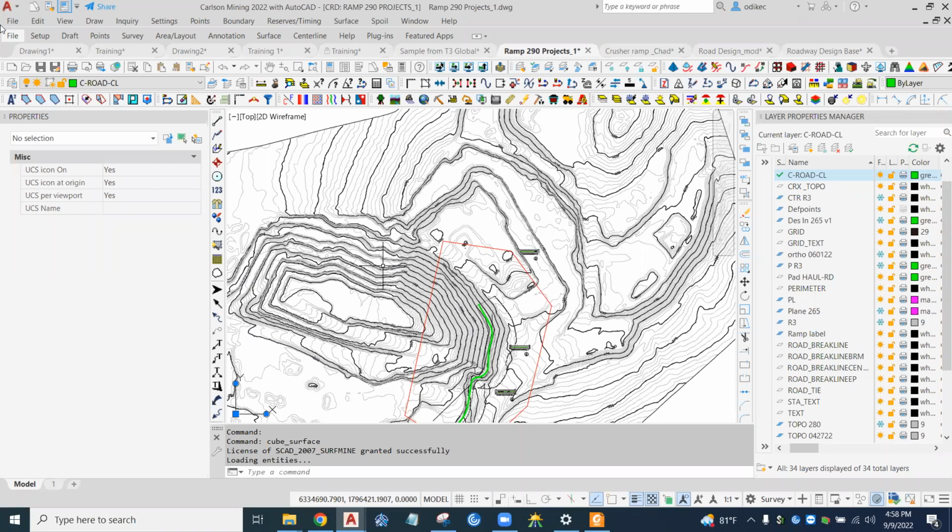But isn't that the same thing that the Surf PL that we just used does? Because I've always used that, especially when I design my wall. I would just use Surf PL, use the Surf PL intersecting line as a guide, and just do an offset on both sides. And I'm able to create the road as a result of that. Yeah, but that's not the same tool though.